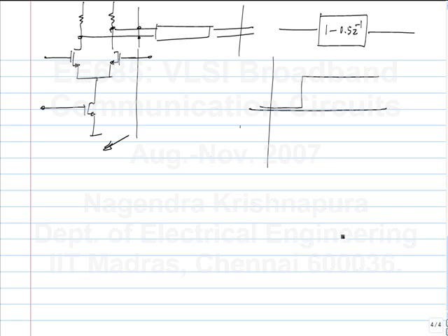What is the step response of this? So it will become 1.5 here, and it will stay that way for one symbol period, right? Is this clear or no? And it becomes 0.5, not 1. And the DC gain of this is 0.5.